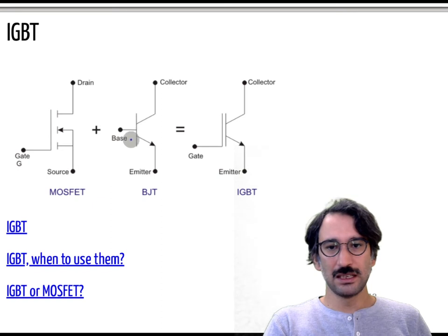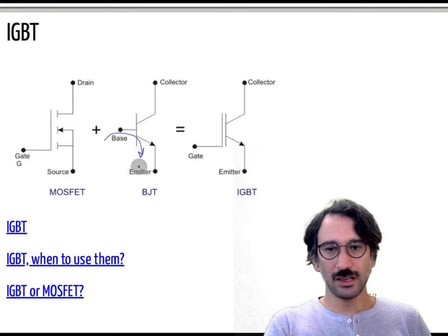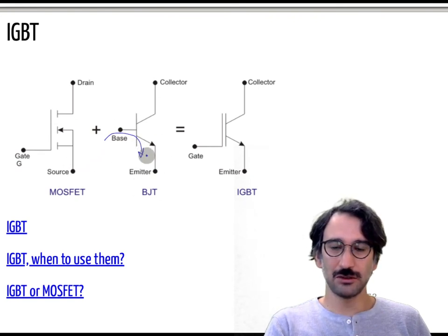Okay, so IGBT is basically a hybrid transistor. It is like a BJT for the power stage, but instead of getting all the current through the base, like in a more analog system, if you remember it from third year, it is combining MOSFET and BJT.